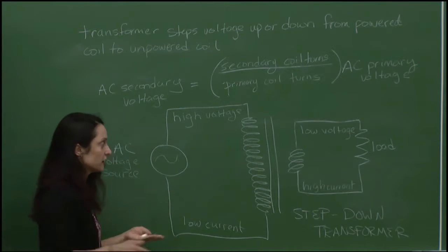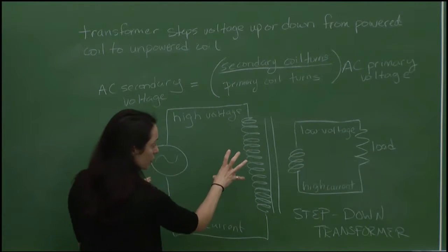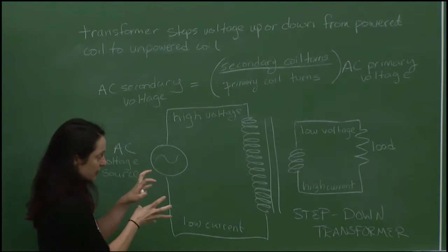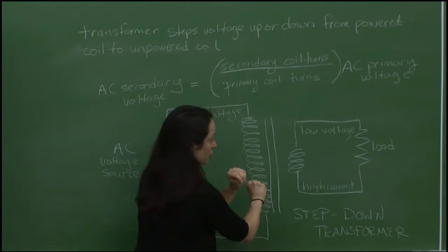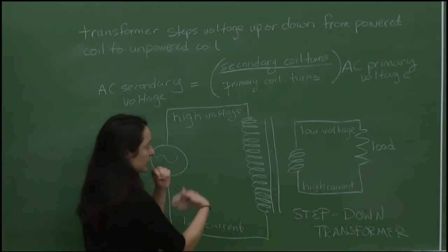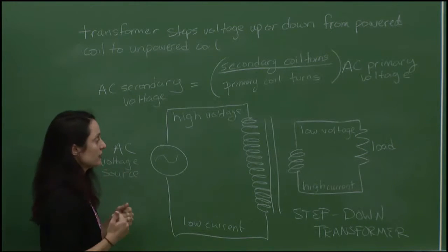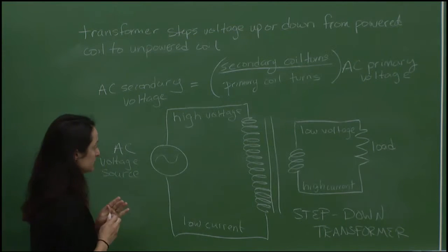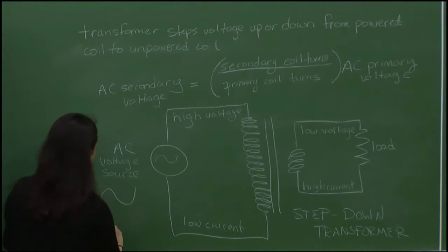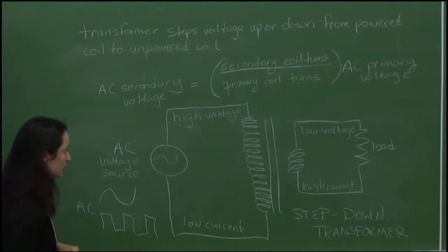It's just sitting there. You have to have this repetitive pattern on the coil to induce a magnetic field, to store that energy in a magnetic field, almost like an inductor, and then shoot it across the gap because of that repetitive signal. And this could be a sinusoidal wave, it could be a square wave. It's just got to be some sort of pattern that's not a constant held DC. So this could be a sinusoidal wave, it could be a square wave, some sort of AC power source that's alternating in a pattern.